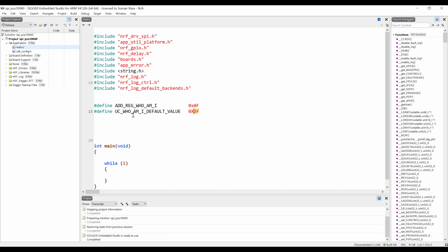I'm going to use these constants because they are similar in the library as well, so later on in the next tutorial we will see that. Also, we need to define the buffer size for SPI communication. Because I'm communicating by transmitting 1 byte at a time, I'm not going to use a very high buffer size, so let's set it to 8 bytes.